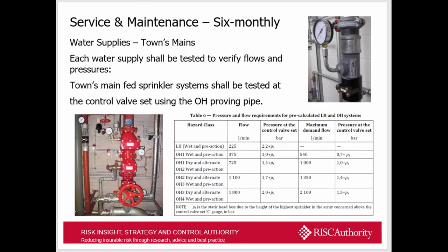Also, if you have a water supply, you have a pump and tank, you have a pressure tank, you have duplicate pumps, etc. You need to do a flow and pressure test to ensure that these are providing you the requirements needed to supply the correct flow and pressure in the fire area for your sprinkler system.